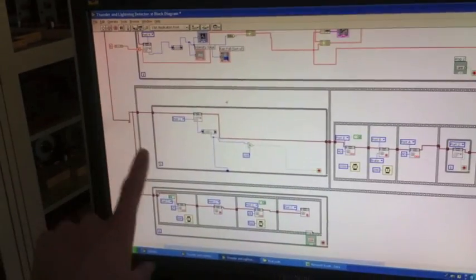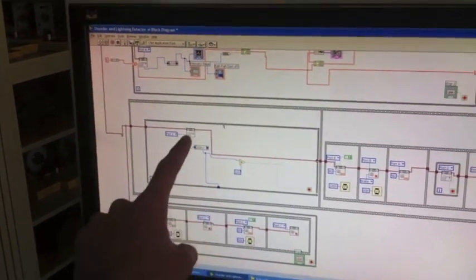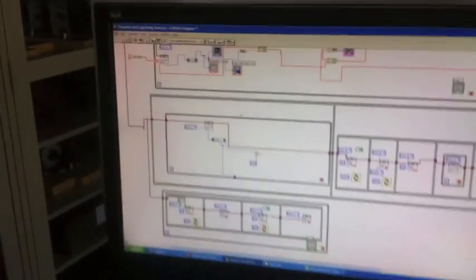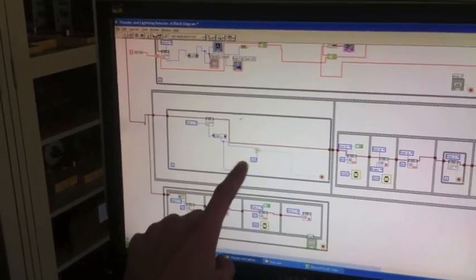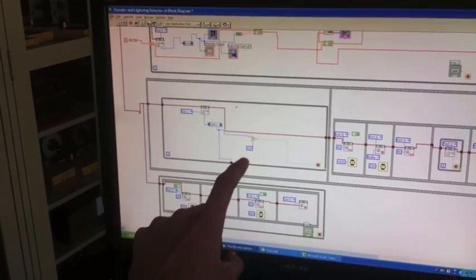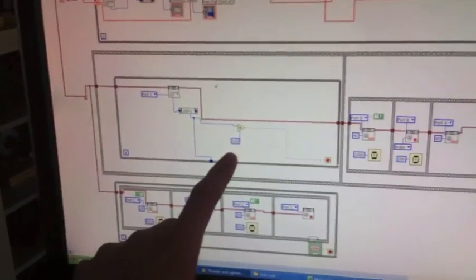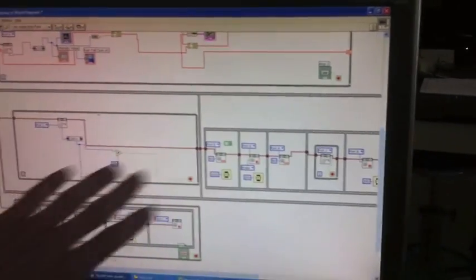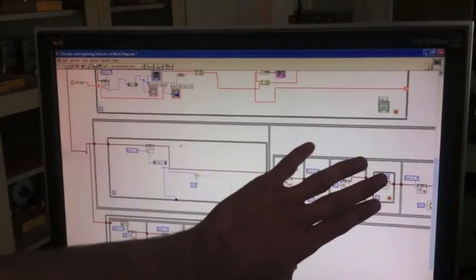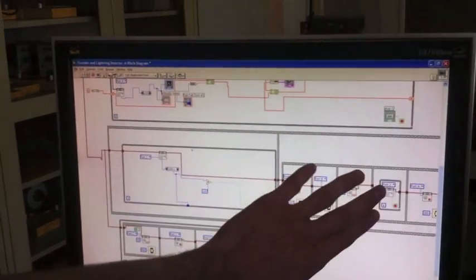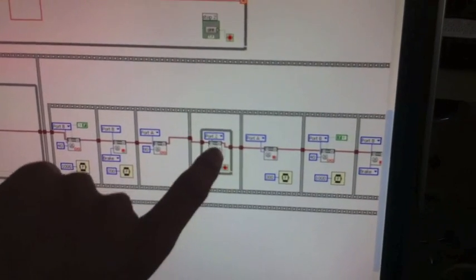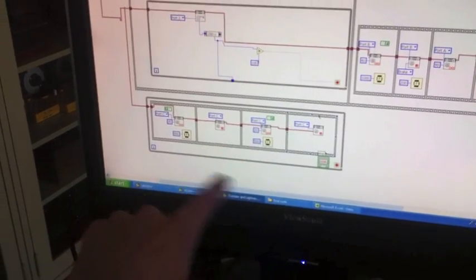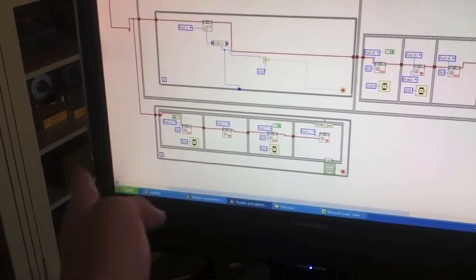The first cell is basically saying when the lightning, this says touch sensor, but it's actually hooked up to where our light source is coming in, and it's saying when light gets above a certain intensity, which we made this number 100 based on what's coming into the NXT, this will stop and go to the next cell, which will turn the motor on. So once it detects light, it'll turn on the garage door and the dog will move forward until it bumps into the back of the house, and then the garage door will close behind it. The bottom part is a while loop telling the solar sensor to go back and forth.